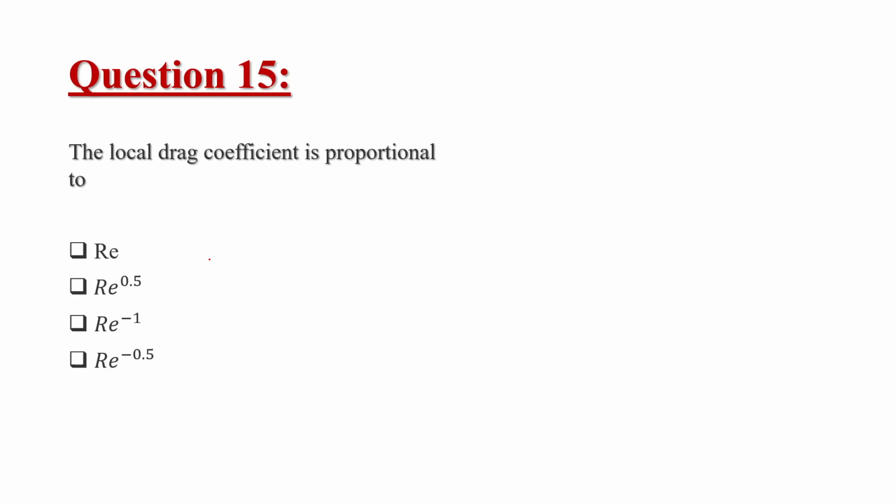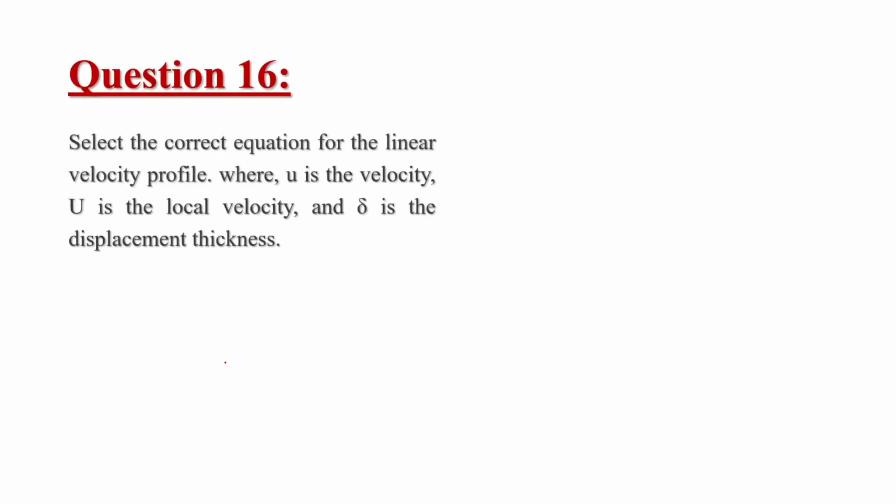This eddy is not only in the central region, but it will be created towards the center in various different regions, like here and here. So they will all try to average out this velocity. That means instead of this u max to u0, they will try to balance this velocity. Instead of having this much large difference in velocity, due to this balancing effect, we will be having a rather flat velocity.